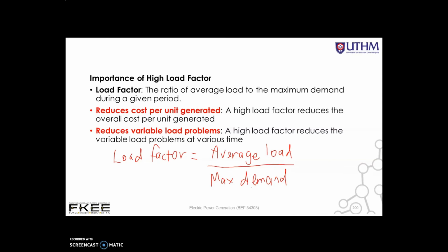If the system has a high load factor, it can reduce cost per unit generated. So a high load factor reduces the overall cost per unit generated, number one. The second importance is that it can reduce variable load problems. A high load factor reduces the variable load problems at various times. So that is the importance of the high load factor.